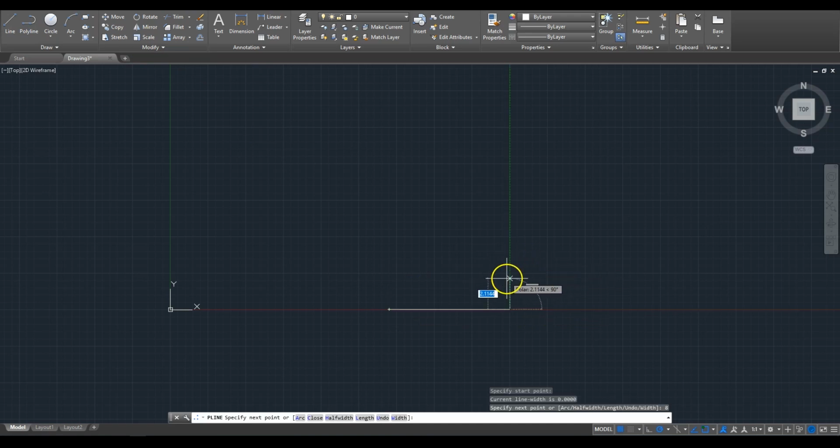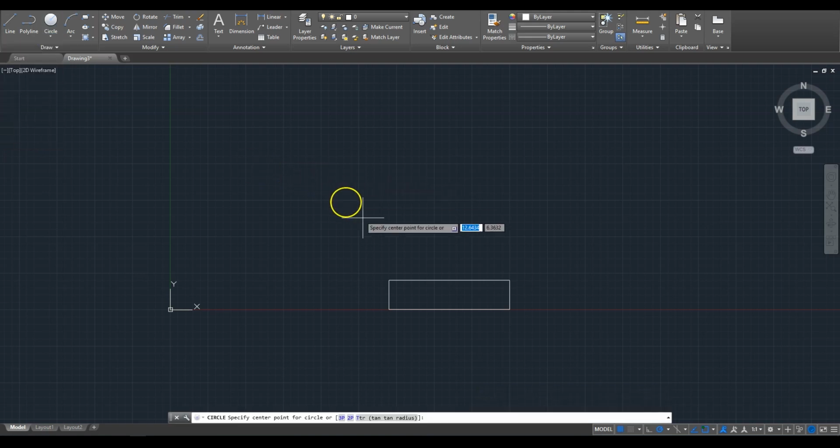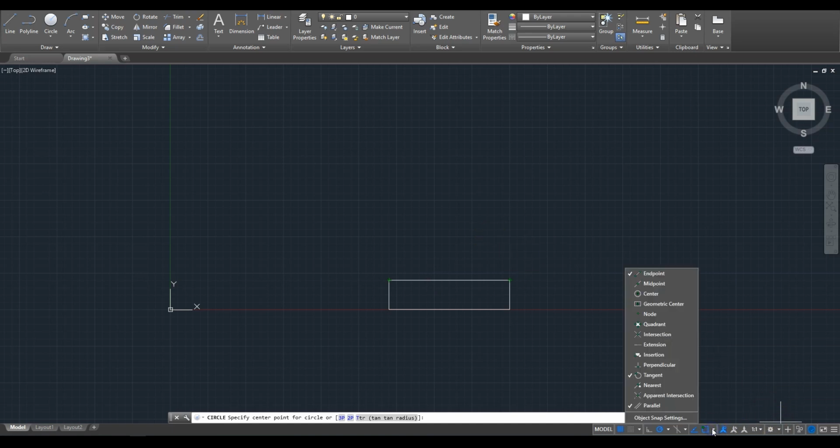When constructing geometry in AutoCAD, use its built-in inferencing and snap features for ease of construction. By just hovering over endpoints, I'm able to align myself and create nice, crisp angles in the desired geometry that I want. I'm attempting to draw a circle here, but I can't get it at the center point here. Well, that's where we go into AutoCAD snaps.